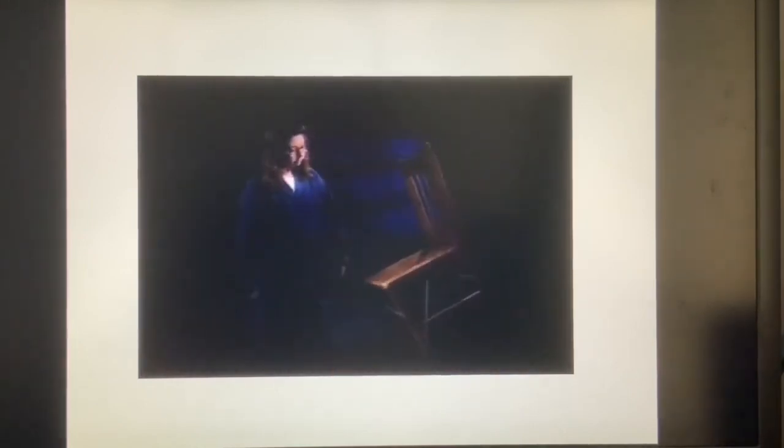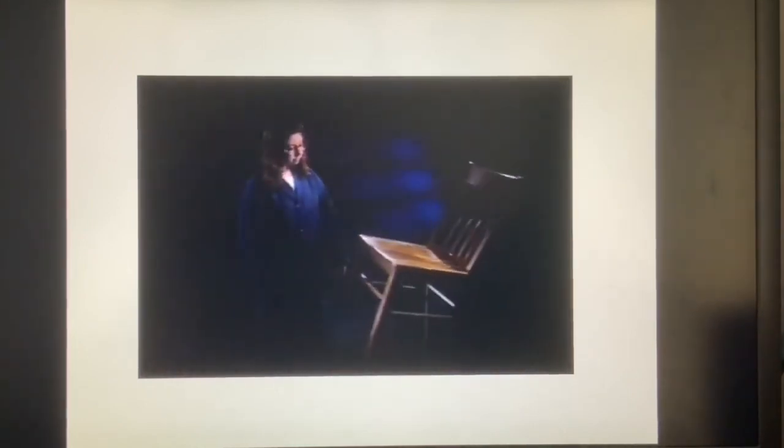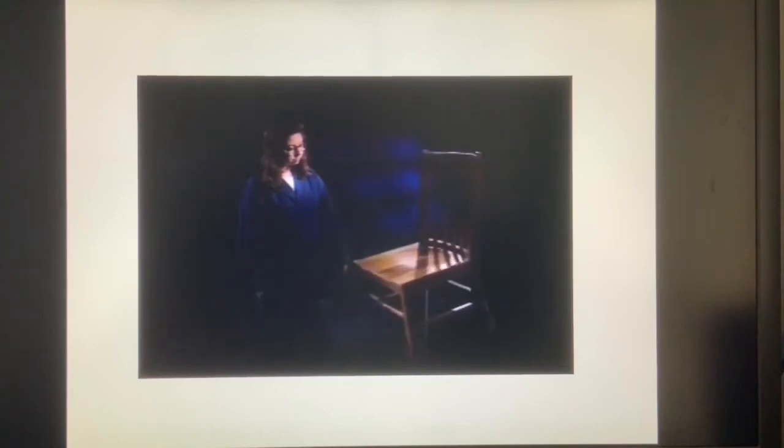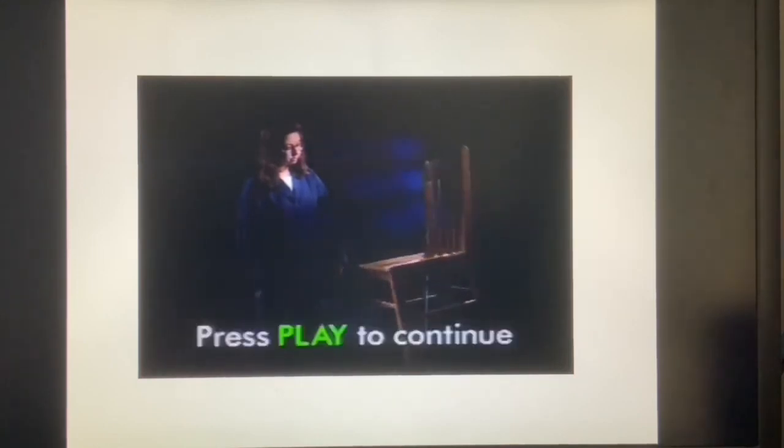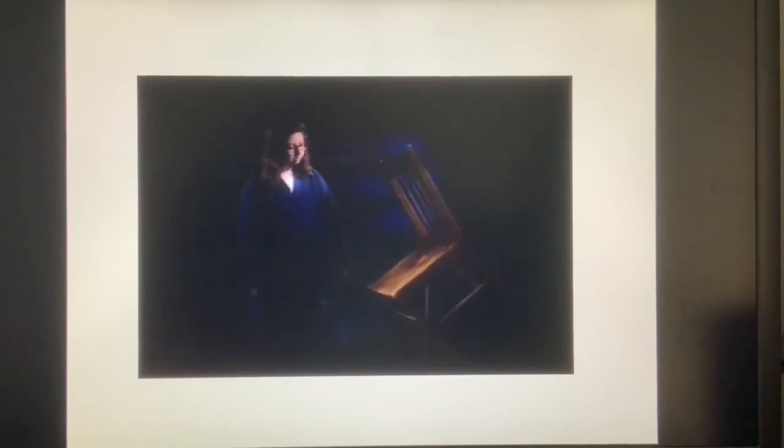The chair is now stable in all orientations and can be swung vigorously without tipping from its support. Why is the chair so stable? Weights have been added inside the legs, which lowers the center of mass to below the point of support.